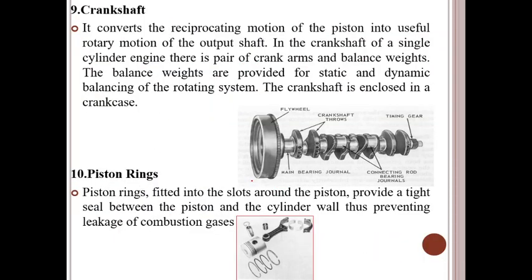Now another component, the crankshaft. What is the crankshaft? Look at the design of this crankshaft, guys. It converts the reciprocating motion of the piston into useful rotary motion at the output. Reciprocating motion means the to-and-fro motion of the piston, which the crankshaft converts into rotary motion.